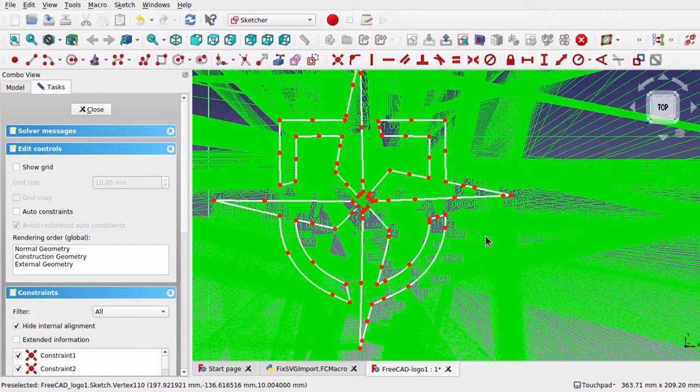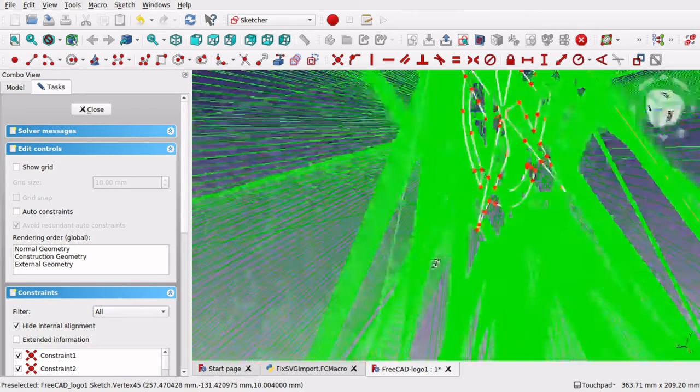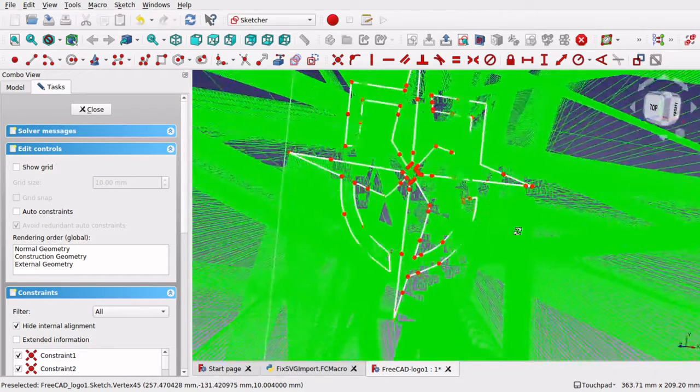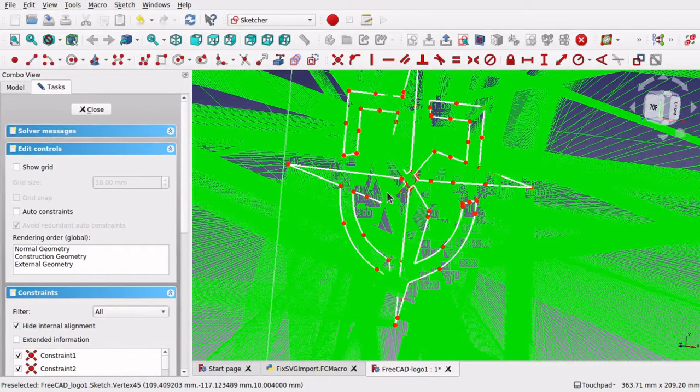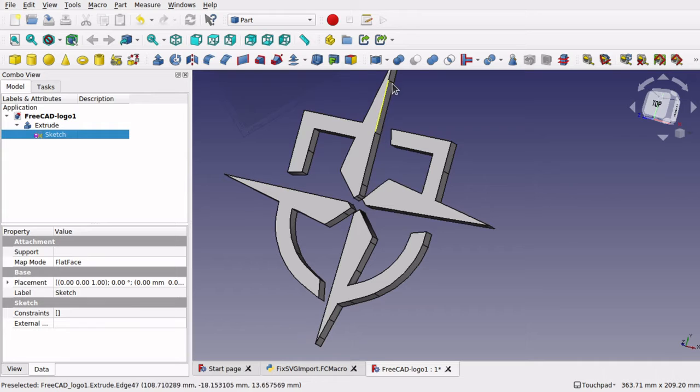Doing a chamfer and a fillet on a complex b-spline with all these combs is not going to work. You can obviously do other operations to boolean parts into this or remove parts from this, but chamfers and fillets are going to cause you a bit of an issue. But there is a way around that.